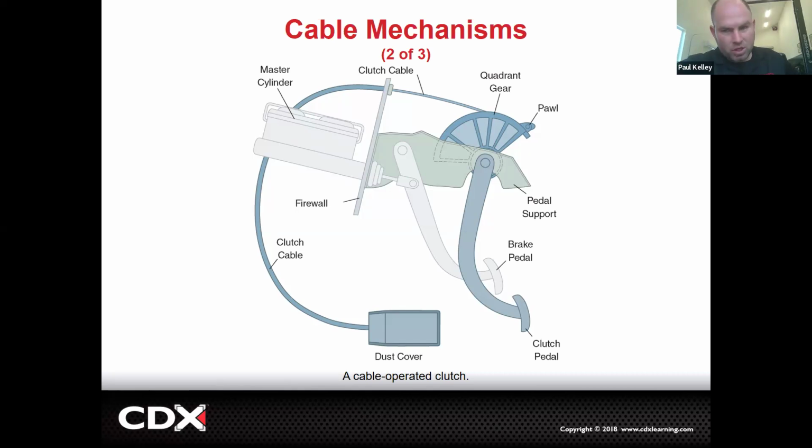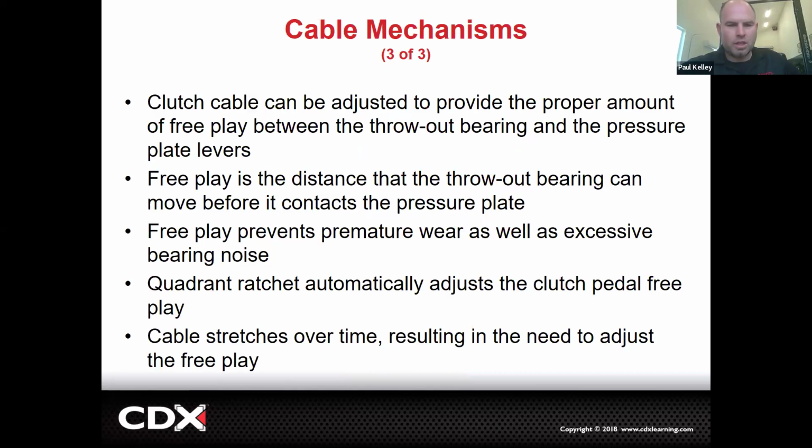And then sometimes, though, I will say, as the clutch disc wears, we should loosen it. But especially if there's friction, the cable can actually stretch, right? So in the automatic adjustment type, we're also worried about cable stretching. And they do, and they can. It could go both ways. Makes sense. If the disc wears, the cable gets tight, but if the cable stretches, the cable gets loose.